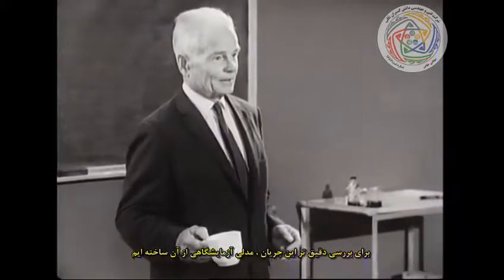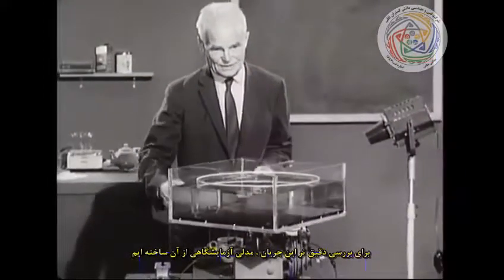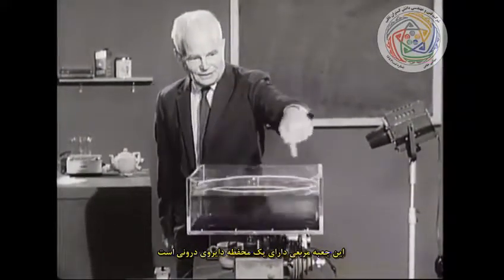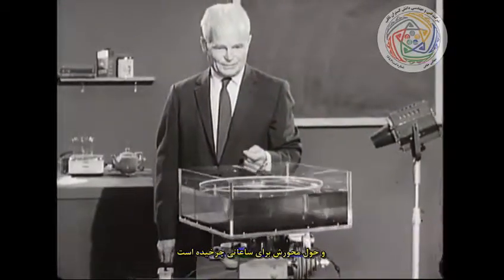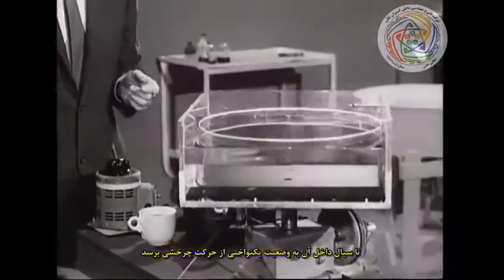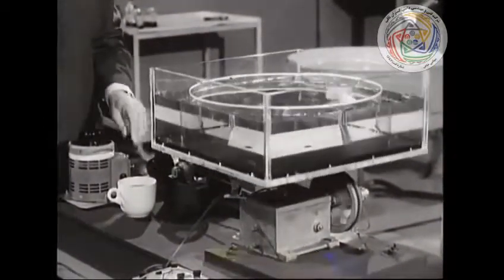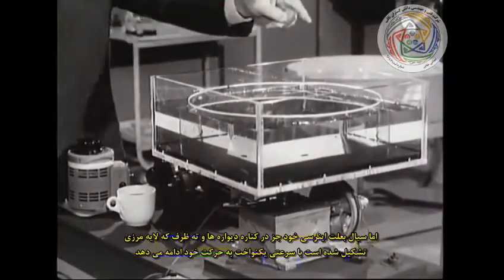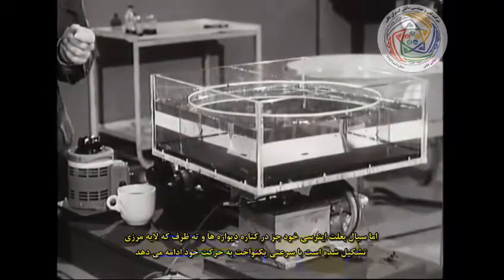We've made an experimental model of this flow in order to examine it more closely. This square box has a circular container inside. It has been rotating around its axis for a couple of hours, bringing the liquid inside to a state of uniform rotation. I can stop the rotation, but the liquid, due to its inertia, will continue to rotate at uniform velocity, except near the wall and the bottom, where a boundary layer will build up.